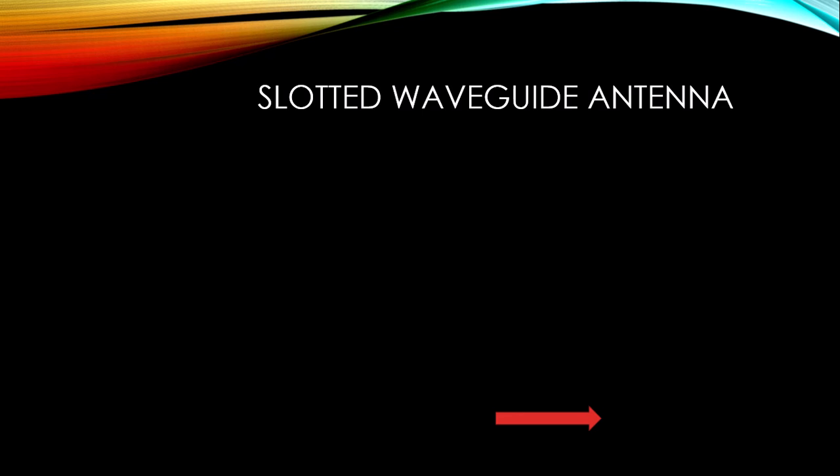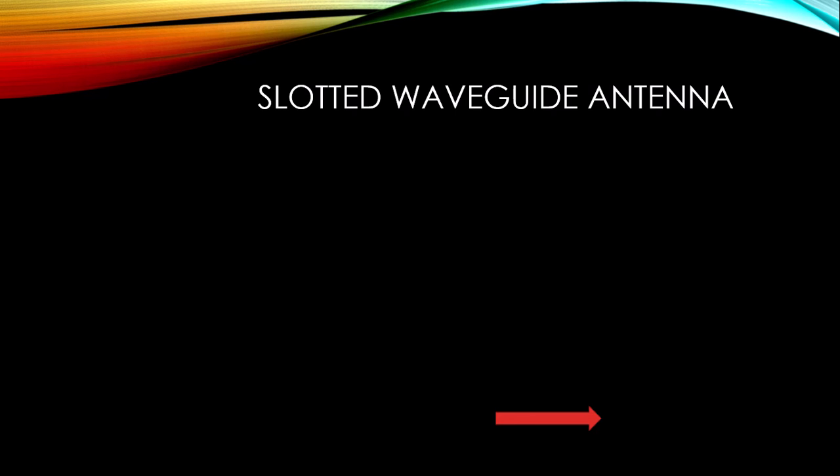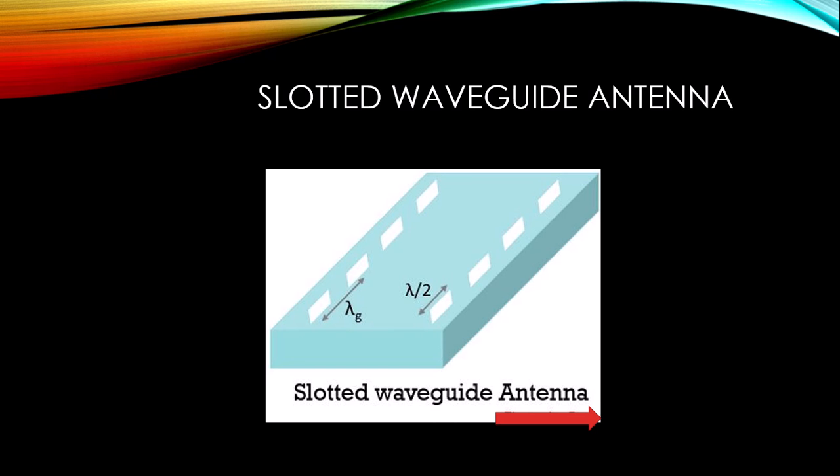The slot in the conducting sheet can be made in any convenient shape, so the annular slots are slots of circular shape that are present on the metallic sheet. The ease of construction and analysis highly facilitates making rectangular or circular slots. A narrow beam of radiation is produced by the annular slot antenna.